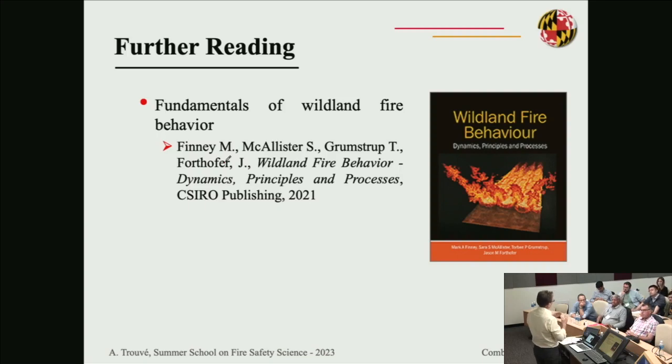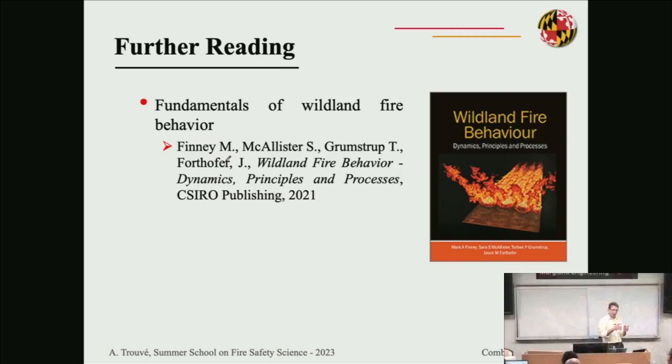Well, I'm not sure, because your last comment takes me in another direction. The flame description as a solid body, I think you have to be very careful, and I think some of the work at Missoula has shown the importance of these buoyant instabilities. That means that even a line fire is not two-dimensional, it is three-dimensional. You're going to have peaks and troughs, so that air can go to the other side of the flame without being deflected if you account for the three-dimensional structure.